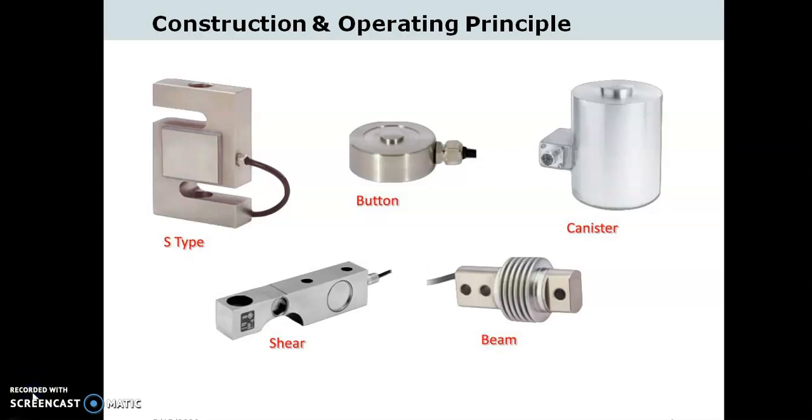Load cell consists of an elastic element. This elastic element is made up of steel alloys, which are homogeneous materials. The basic design constraints are relative size and shape, density of material, modulus of elasticity, strain sensitivity and dynamic response. The elastic elements used are designed and shaped according to the specific requirements. The elastic elements of different shapes are shown in this figure.